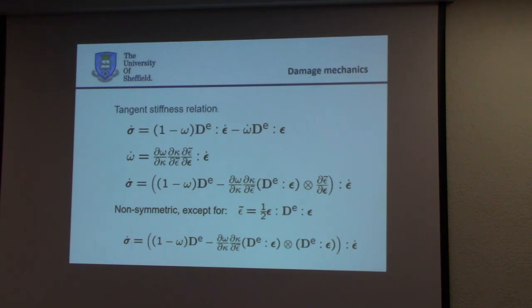Then you feed your updated displacements into your constitutive relation at integration points. So you transfer the variables, displacements in nodes, to strains in integration points. At these integration points, you compute the stresses. And from that, you compute the internal forces in the device.